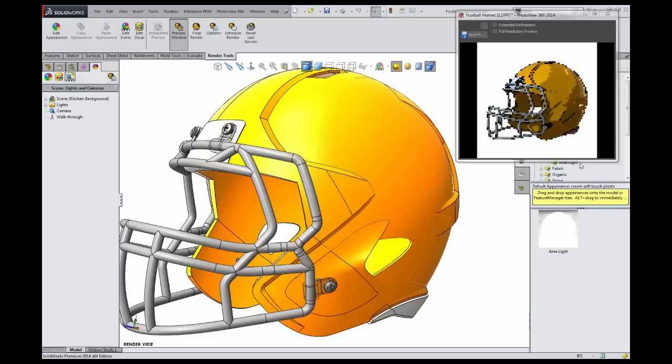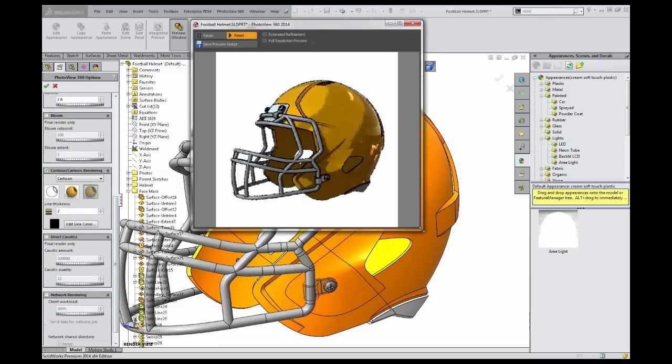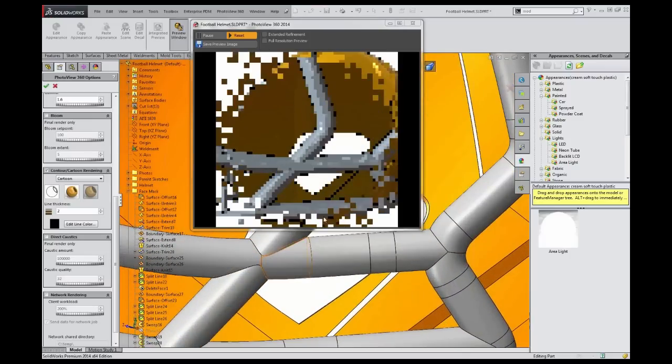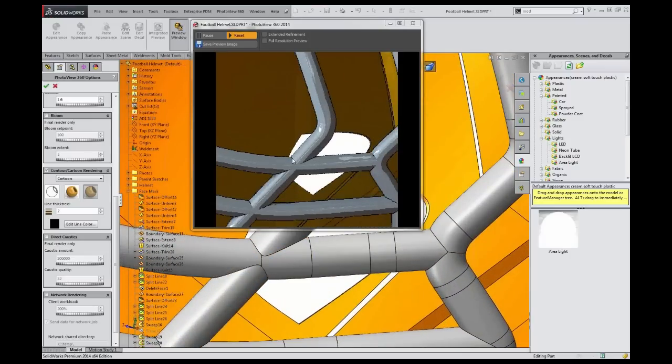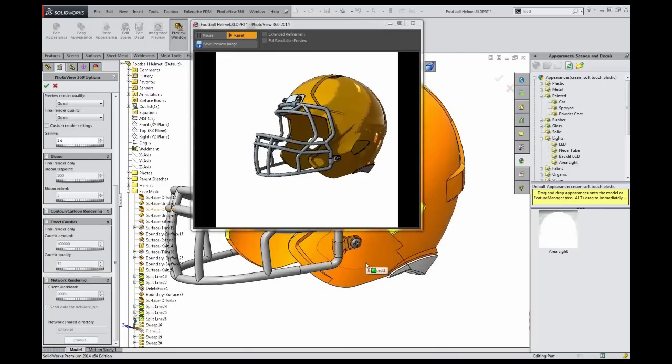So now that I've got my settings right, what I'm going to do, actually let me turn off that contour rendering. I accidentally turned it on. Here you can see what it looks like. It highlights the edges with bold black lines because that's what I've got selected, and it's really cool. It'll fade out the edges as well, so it's not just highlighting all the model edges, it's just outlining the best it can, and you can see all the model edges on the face mask that it's actually omitting. If I take a close look there, it does a nice job of outlining the edge and fading it to no edge where all those faces intersect. Pretty cool. But I'm going to turn that off for now. We're looking for a more realistic look than that.